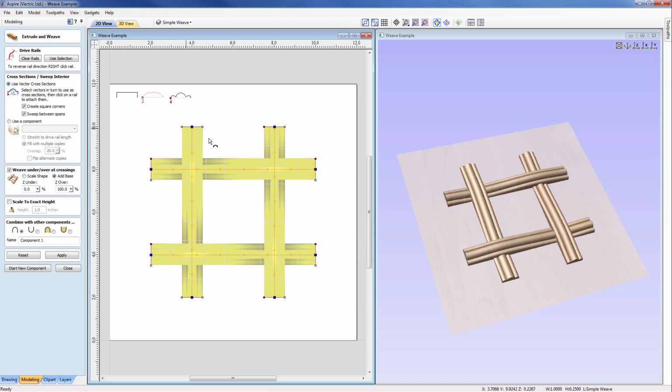And then I'm going to go across to the drive rail next to it and select the box cross section and just map that to top and bottom. Okay, and then come across and apply. So now we'll have quite a different effect. We've got the two lateral drive rails that are using the ridge shape, and then we've got one vertical with the rounded and one vertical with the box section.